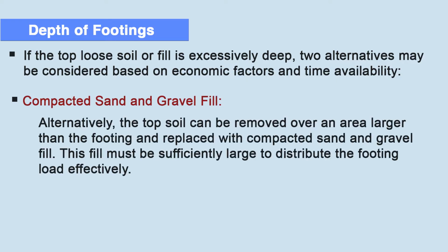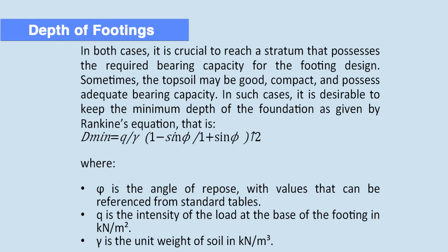And the second is compacted sand and gravel fill. Alternatively, the top soil can be removed over an area larger than the footing and replaced with compacted sand and gravel fill. This fill must be sufficiently large to distribute the footing load effectively. In both cases, it is crucial to reach a stratum that possesses the required bearing capacity for a good footing foundation design.